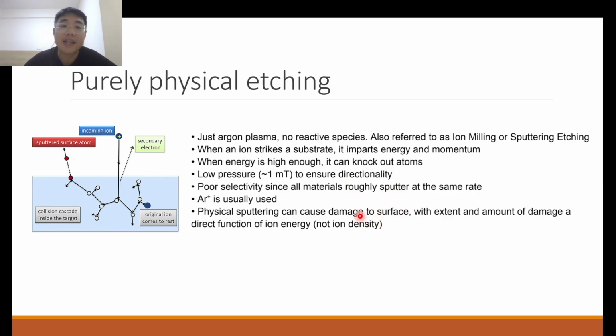At the same time, it can also cause damage to the surface, and it can make the process dirty because of re-sputtering. The material you bombard out falls on other places of your wafer because it's not chemically changed. It was a solid, it still is a solid. You can think of it like if you drill a hole in the wall, all your plaster dust, or dust from your concrete, will drop somewhere. In the case where it's a vertical wall, it drops on the floor, but your wafer is horizontal, so it can drop other places on the same flat wafer, so that's not good.